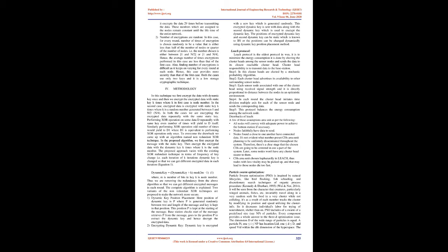3. Redundant XOR Technique. This technique uses symmetric key cryptography. The architecture, constraints, and limitations involved in WSN are far different from real-life computer networks. Hence, not all security algorithms can be used in WSN, as many of them do not meet the energy and storage limitations. Thus we chose the XOR operation as the base of our security algorithm, which is the least complex operation that can be performed in the least time. Encryption of data takes place at the WSN, whereas decryption is done at the BS.